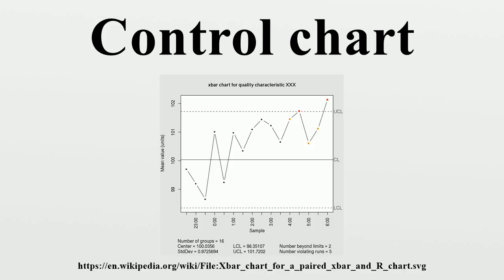Control charts omit specification limits or targets because of the tendency of those involved with the process to focus on performing to specification, when in fact the least cost course of action is to keep process variation as low as possible. Attempting to make a process whose natural center is not the same as the target perform to target specification increases process variability and increases costs significantly, and is the cause of much inefficiency in operations.